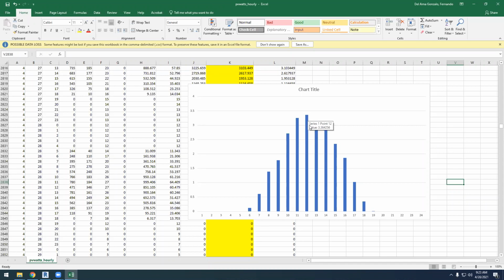Can we rely on this specific day? Well, I mean, the average on April the 28th will be like this. Does it mean that today, without any sun, we are producing this? Well, maybe not today, but the average on every April the 28th, it will be something like that. But this is how this software works. They don't analyze actual data right now. So they have a huge database, and they just have the average solar irradiance, temperature on that specific day.